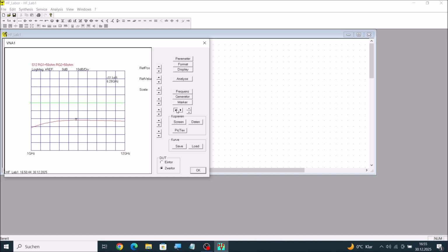So you see the feedback is quite small, starting at 1 gigahertz with minus 30 or better than 30 dB, but it will become greater with increasing frequency, and this parameter will be responsible for the point that some transistor may become unstable in a certain frequency range, but this also we will see later.